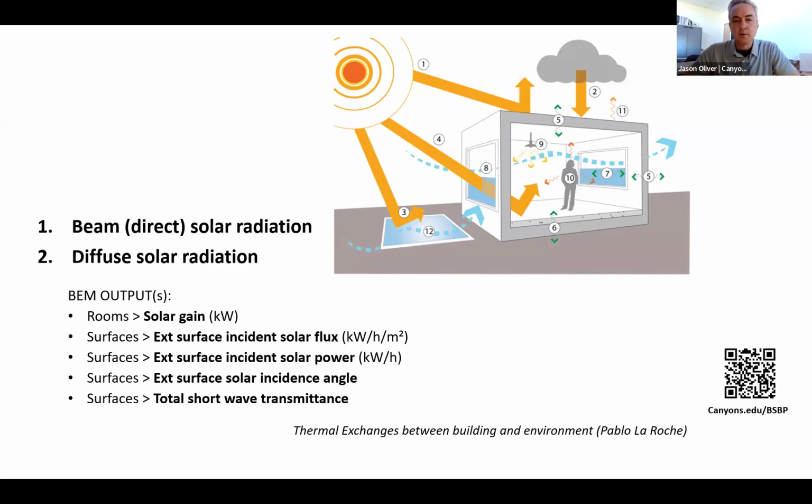So, for instance, solar gain, the solar radiation that's emanating from the sun, either directly or indirectly, because maybe it's being scattered by cloud cover or reflected off of surfaces nearby. We can simulate that solar gain, heat gain for a building, and sometimes we need solar gain to heat a building up in the wintertime in cold climates. But where I'm at in Southern California, we're often trying to combat excessive solar heat gain, so shield against it.